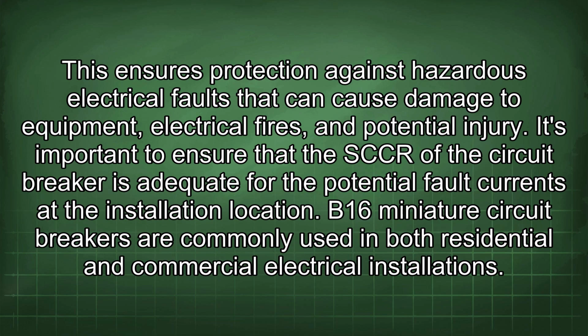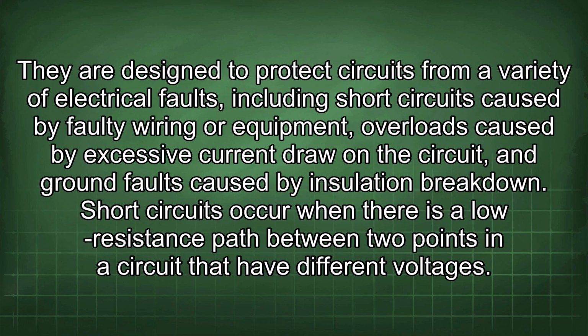It's important to ensure that the SCCR of the circuit breaker is adequate for the potential fault currents at the installation location. B16 miniature circuit breakers are commonly used in both residential and commercial electrical installations. They are designed to protect circuits from a variety of electrical faults, including short circuits caused by faulty wiring or equipment, overloads caused by excessive current draw on the circuit, and ground faults caused by insulation breakdown.